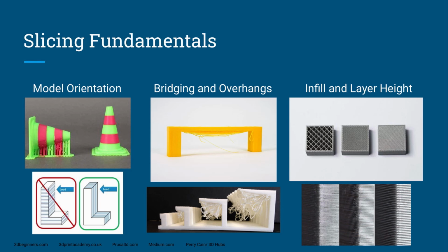Also, the image below that you can see is putting load on a 3D print. So you have to remember your 3D printer is printing layer by layer up and up and up. So if you print that standing straight up, the layers are going to be horizontal to the ground or to the print bed, right? So if you push a load, it's going to crack on those layer lines, right?